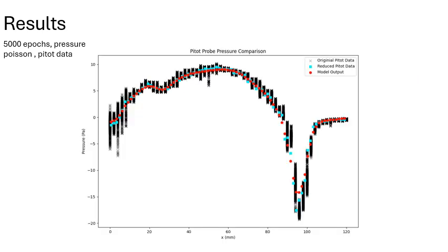So black and blue are our pitot probe actual pressure data, and then red is what the model learned. So it matched the pitot probe data quite well. Even though it doesn't have boundary conditions, this becomes its boundary condition. The problem is PIV data and CFD data are basically unsteady, but pitot probe data is not. It's a time averaged thing. So that means that your average pressure isn't going to catch those unsteady effects that could be a lot lower or they could be a lot higher. And so in the end, you're going to raise the pressure of your whole field,